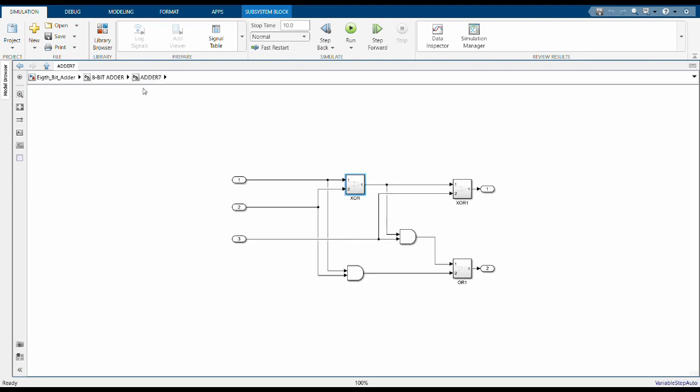We usually end up adding 3 bits when there is a carry from the previous digits. So we add the sum of the first 2 inputs to the carry from the previous step. We add an AND gate to check if the sum of our first 2 inputs is 1 and there is a carry in bit, in which case the carry out bit will be 1. And the carry in bit with the sum of the inputs will be the total sum.